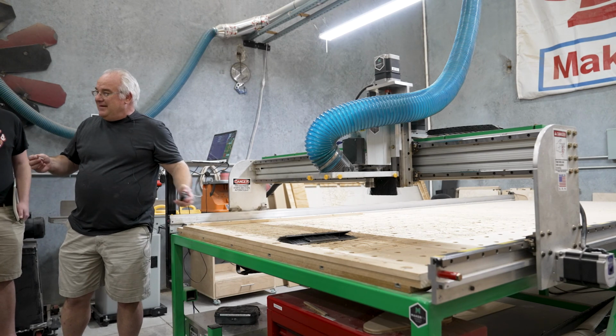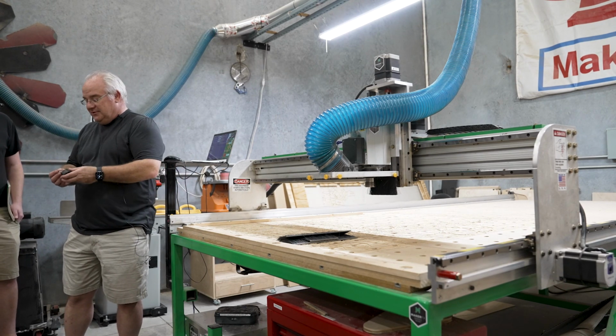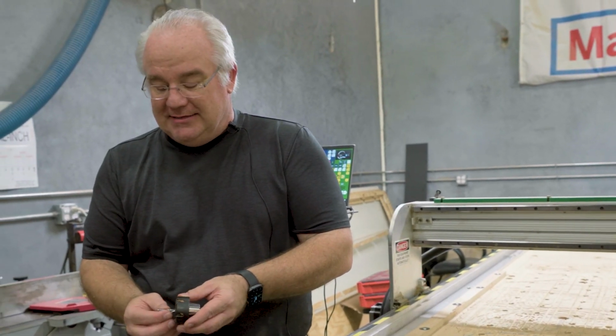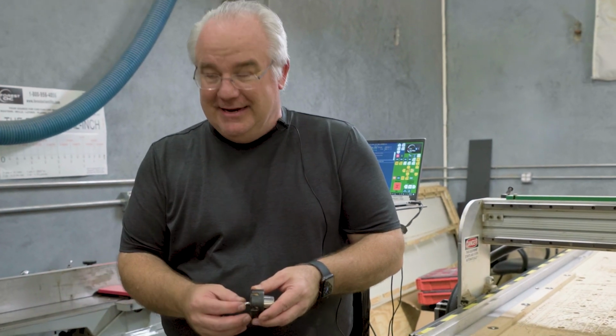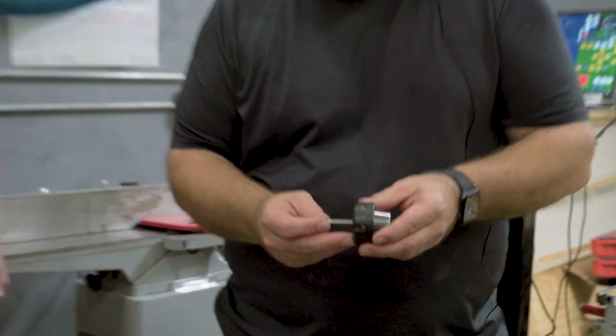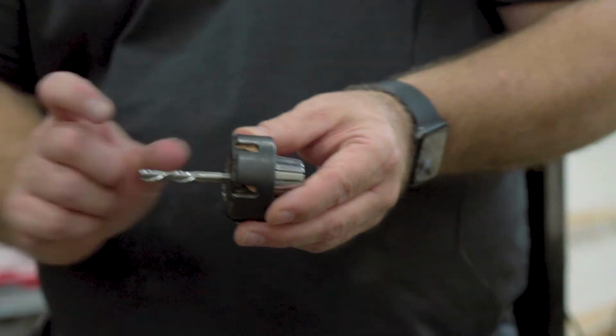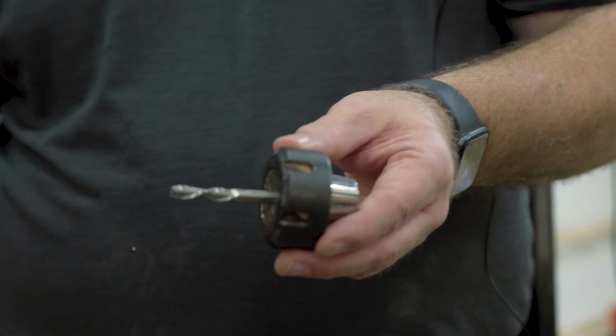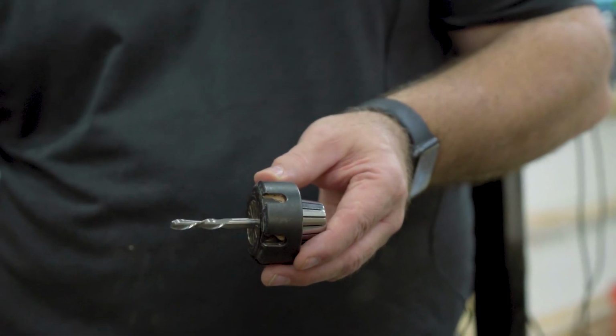So now that's an extreme example, but it illustrates the point that you want to think about how much bit you have out. In my case, I only had an inch worth of bit out, and it didn't have enough room. Once I realized what had happened, I had to adjust the settings so that I had more than an inch and a half of bit out to be able to go all the way through both of those pieces of MDF.